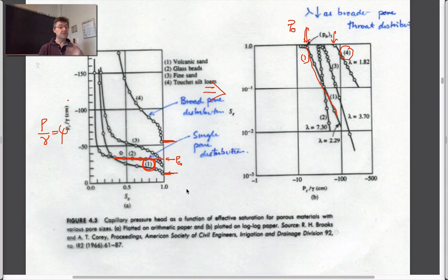So those are the two discriminating factors, the magnitudes of the entry pressures, as to where the 100% saturation curve crosses. The other feature of this is the slope. Here, this is a very flat curve. It means that as soon as we invade at this pressure, we invade everything. So on this curve, we'd expect that as soon as we invade, as we increase the pressure, we don't have to increase this pressure very much to be able to invade the rest of the system. That would be signified on here as basically a vertical line.